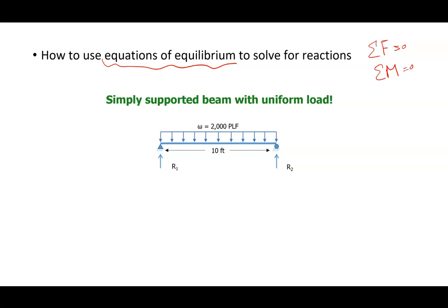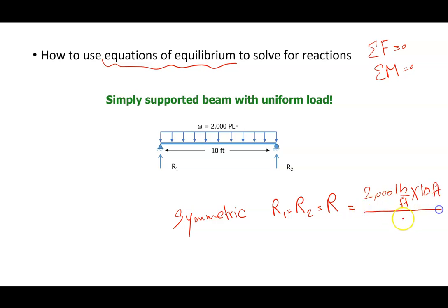Since we have a symmetric system, reactions are equal to each other and they're equal to load times length of beam divided by 2.